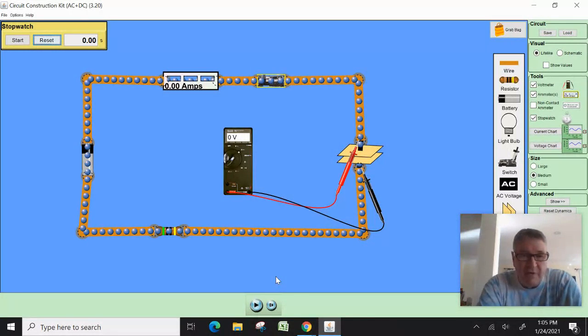Now the reason why the time is important, if you look at the top of the lab, we didn't actually do this lab, but I showed you this lab. The RC is called the time constant. So if you take the resistance and you take the capacitance of the circuit, that gives you a time constant. If you multiply that time constant, the RC product, by 5, that's 5 time constant intervals. And what that means is that the capacitor is done doing what it's going to do. It's 99.3% of the way through what it's going to do. In other words, it's almost totally at equilibrium or steady state or whatever you want to call it.